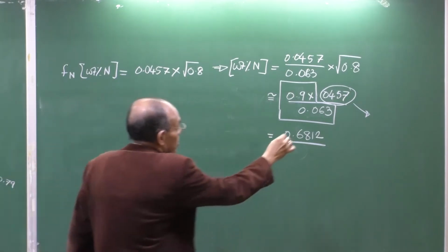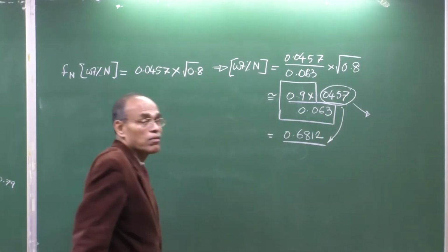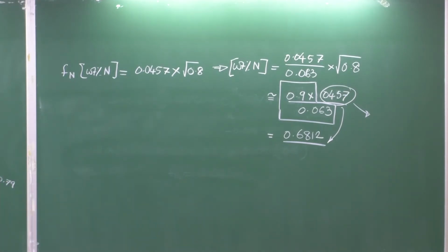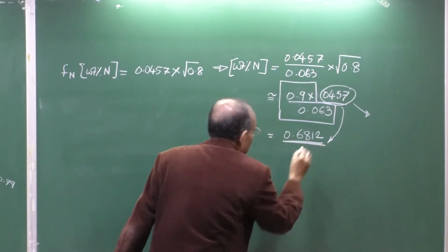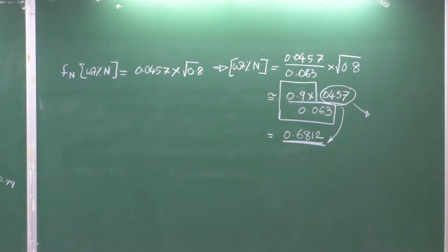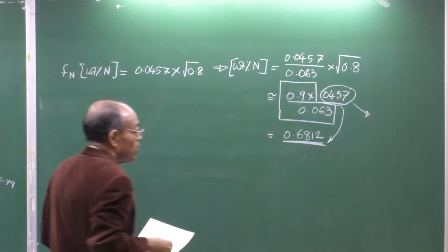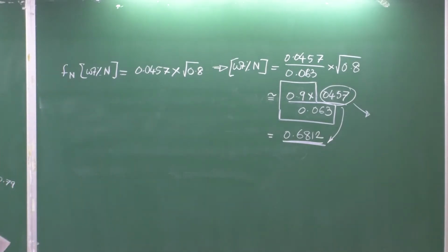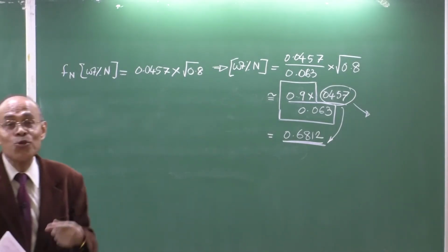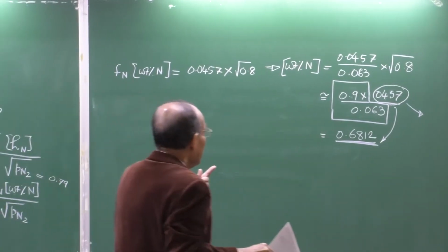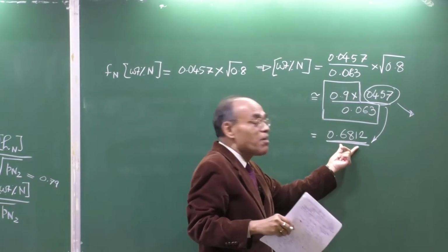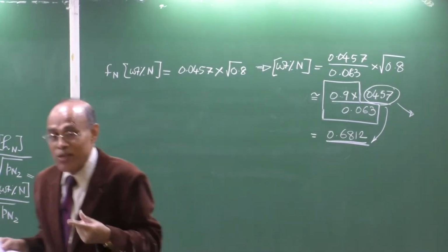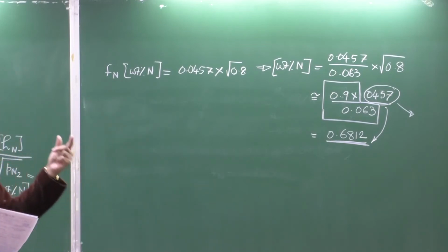So, you can imagine that these alloying elements have increased the solubility of nitrogen considerably in steel, and the steel now contains about this much nitrogen. You can compare the values at 1 atmosphere pressure for a pure iron melt versus an alloy steel melt, and then calculate for yourself. So, you can understand now. As I said, once you solve the problems, you should be able to extract more. Merely getting the number is not enough. You must understand the implication of this problem. This gives us several messages.